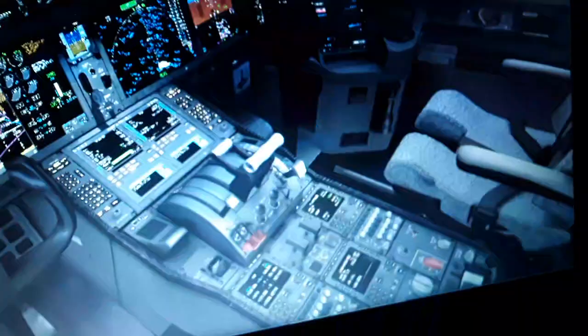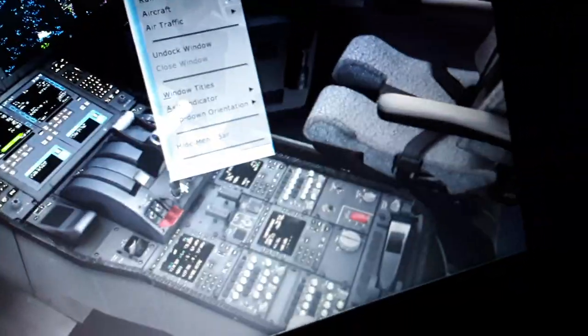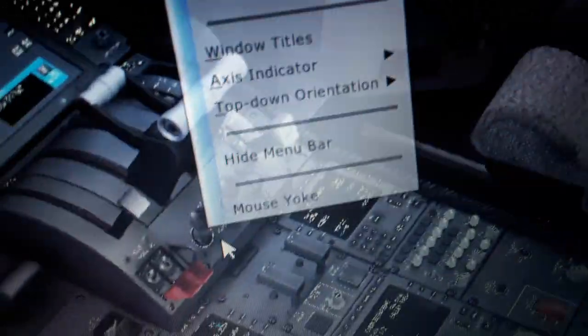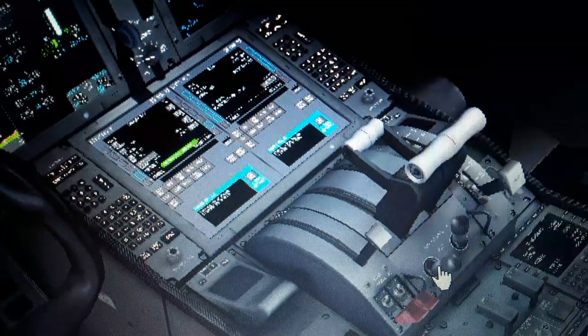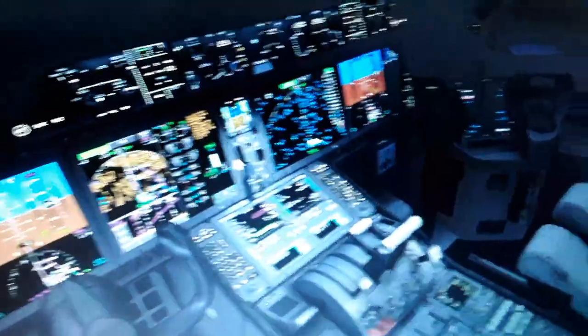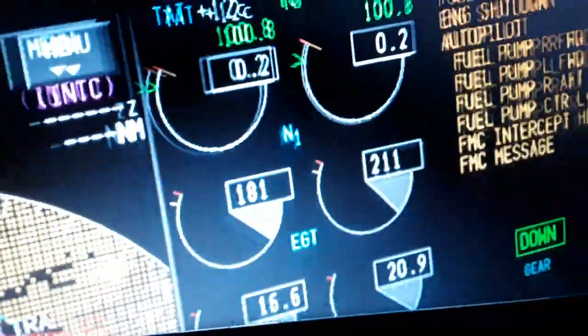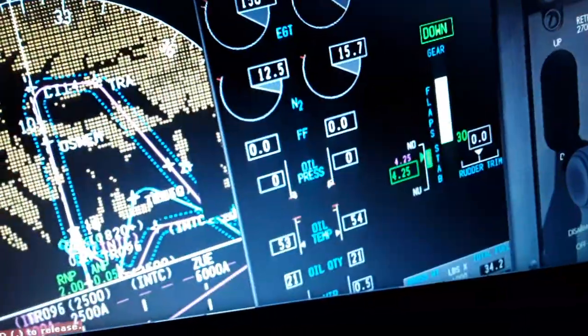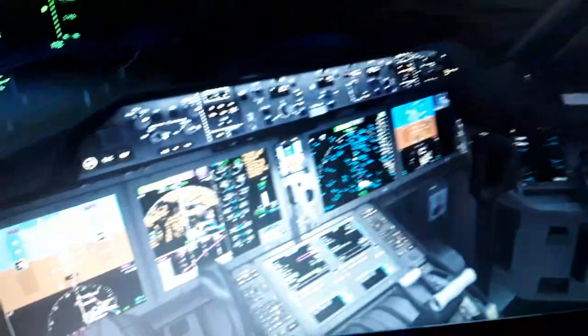We're going for the engine start demonstration. So we turn off both fuel flow, left and right, as you can see. So we turn off over here the fuel flow, left and right engine. You can see here we have the engine shut down right now, so there is no spinning. The N1 decreases, exhaust gas temperature also, N2. You will see in the overhead maybe a reset now.